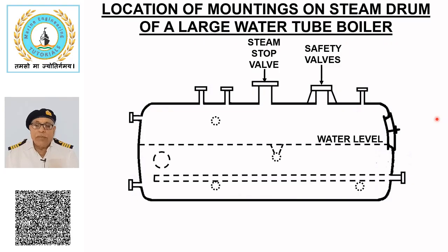Main boilers on steam ships are equipped with steam stop valve on superheater outlet header to provide superheated steam. Steam stop valve is often equipped with a small bypass valve for warming up of the steam line before opening the steam. This arrangement prevents damage to steam stop valve from wire drawing effect of the steam.